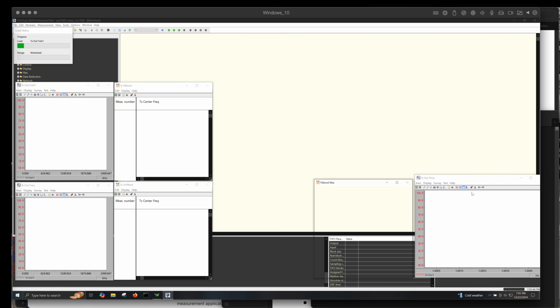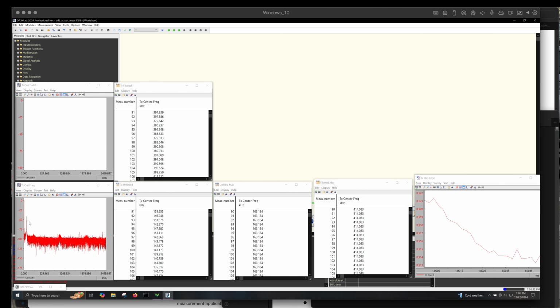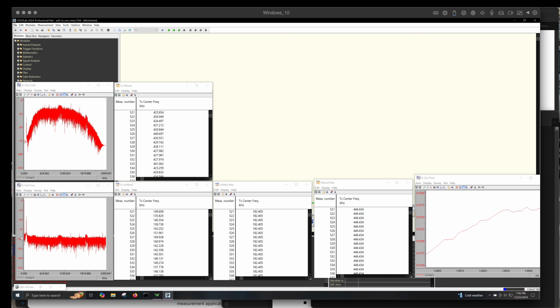Hit 2.5, so we're going to switch over to the main sheet. You can see we're running here. Interesting, even though I haven't enabled it, it looks like I have some sort of leakage from the onboard oscillator on the DDS dev board, since the center of this is 1 megahertz and the onboard oscillator driving the DDS chip is 25. Was it 25 or what was it? Can't remember. This seems to be right about where it is.